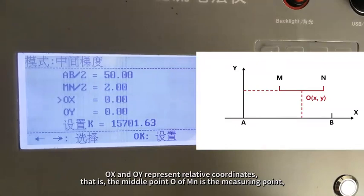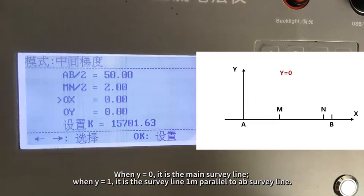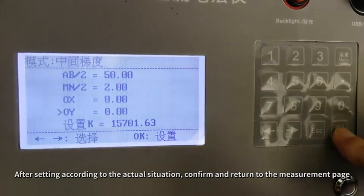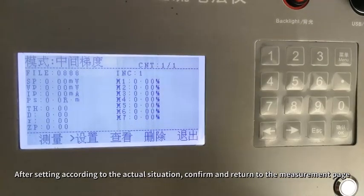Ox and Oy represent relative coordinates, that is, the middle point O of MN is the measuring point. AB is the x-axis of the coordinate axis, and the y-axis data is the parallel distance between MN and the AB survey line. When y equals 0, it is the main survey line. When y equals 1, it is the survey line 1 m parallel to the AB survey line. After setting according to the actual situation, confirm and return to the measurement page.